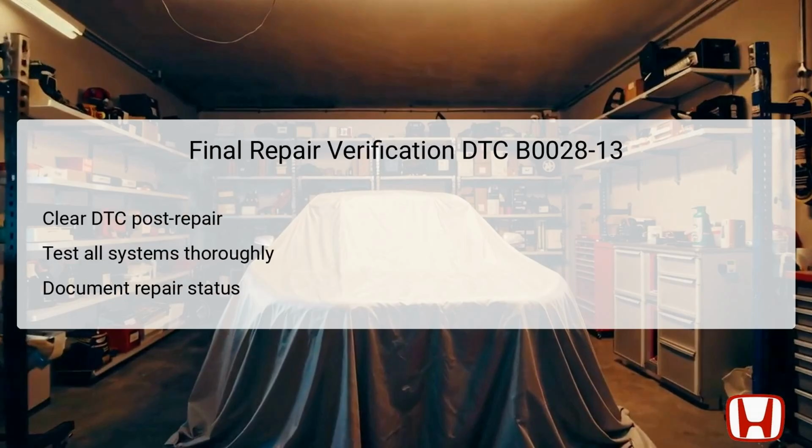Upon completing the necessary repairs or component replacements, it is crucial to perform a final verification process to ensure the integrity of the repair. Start by clearing the DTC from the vehicle's memory using a Honda Diagnostic System, HDS, or an equivalent scan tool. Following this, conduct thorough tests on the airbag and SRS systems to verify that all functionalities are operating normally and no further DTCs are present.